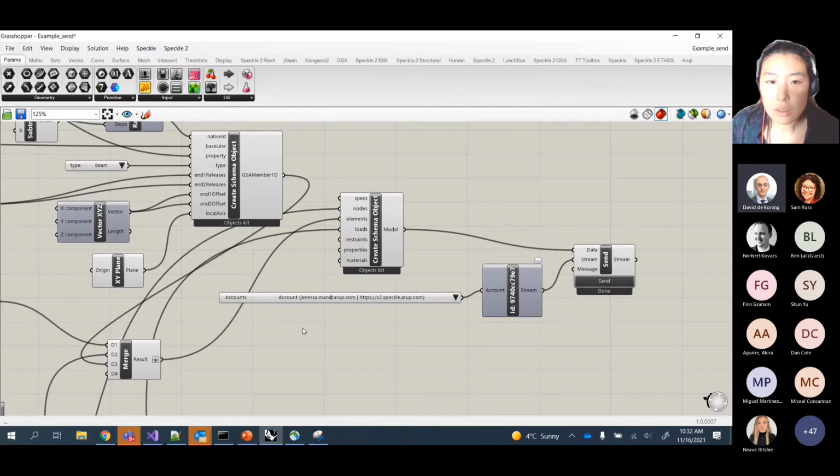We've got a question about sending. Now that you've got to the send component, how fast is the conversion, and is it feasible to keep the send button always working so that whenever the parametric inputs are changed or there's an evolutionary optimization tool, the data goes directly through to Speckle or ETABS? Mm-hmm. So in Grasshopper, there is an automatic send. In the Grasshopper component specifically, there is an automatic send. So you can continuously stream changes. In the GSA connector, I can't speak for the ETABS connector.